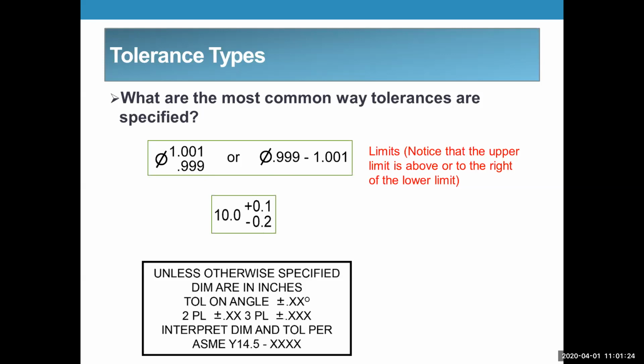When you're turning a shaft, you're starting with a piece that's oversized, and then you're slowly bringing the OD down to where you want it. So this is the number you're going to shoot for to begin with, and if you happen to miss it, then hopefully you still wind up somewhere in between these two limits.